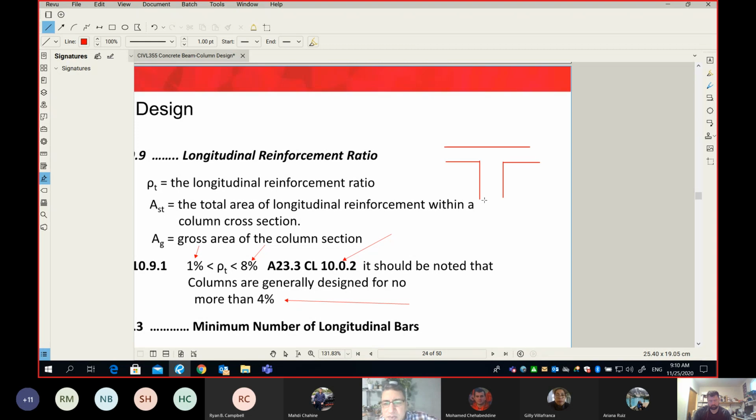Look at this, please. So we have our rebar. We make sure our rebar extends beyond the level of the slab, just like so. Those are called the column starters. This projection of the rebar on top of the floor level, we call them starters.